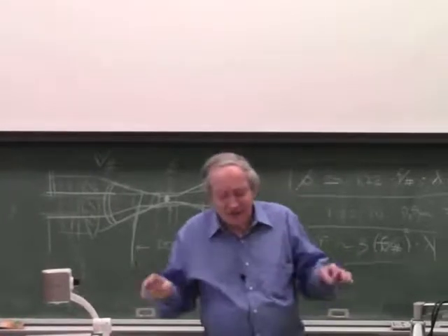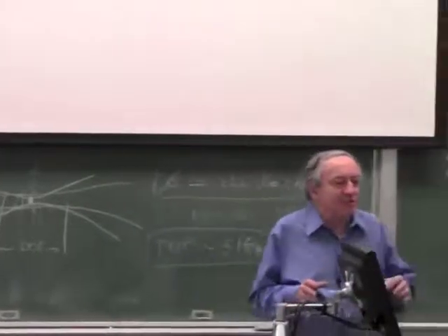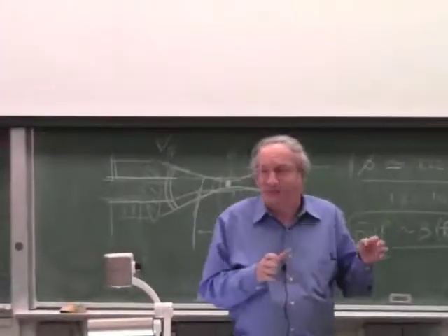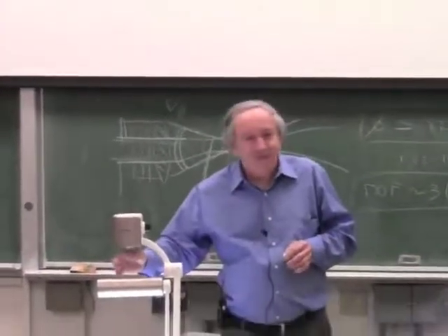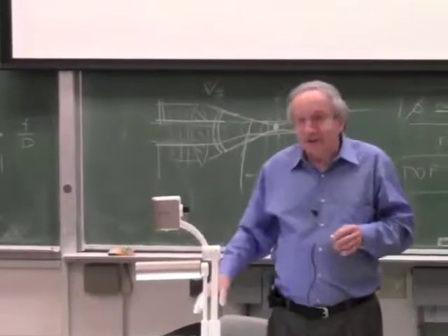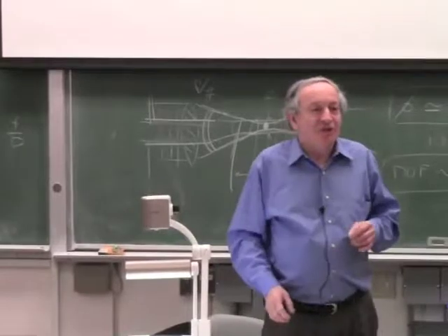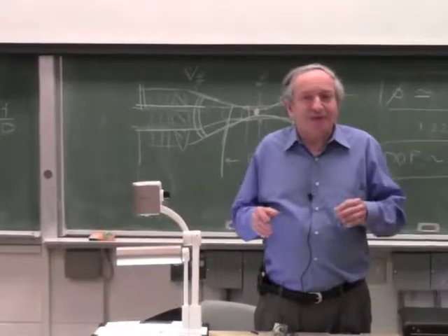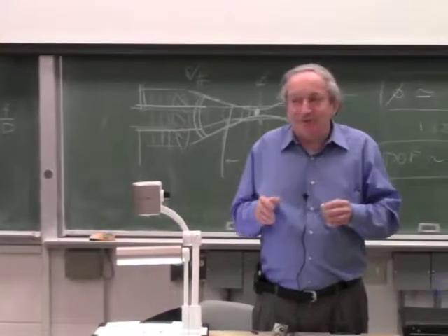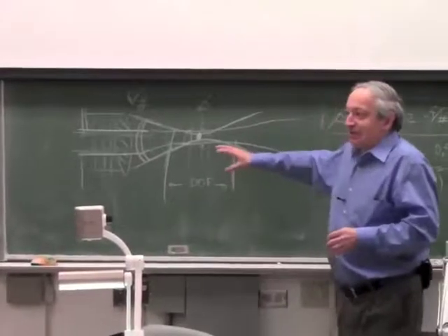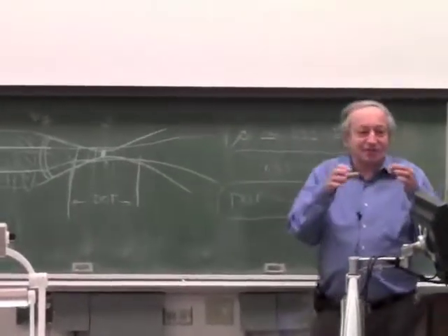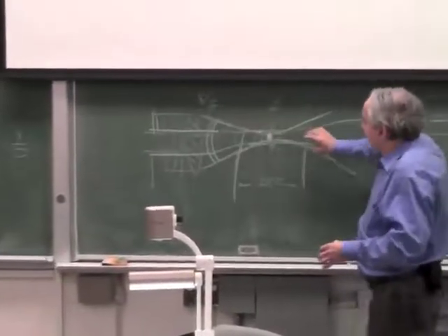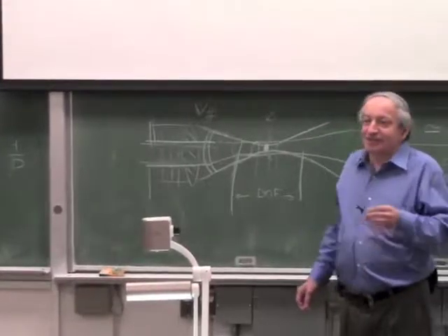Okay, so this was a very, very quick introduction, but the main concept to take away is that if you take any optical system, and we are talking about optical sensors, that's what we care about, you stop it down, which means you make the hole smaller, you'll get a lot less light by the square, but you will get better depth of field, and everything will become better and better until suddenly you won't be able to resolve anymore, because you're going to hit this limit. So until you hit this limit, things get better and better as you stop a system down. But then, at some point, because of diffraction, it can't resolve anymore. Okay, and then things get worse again.